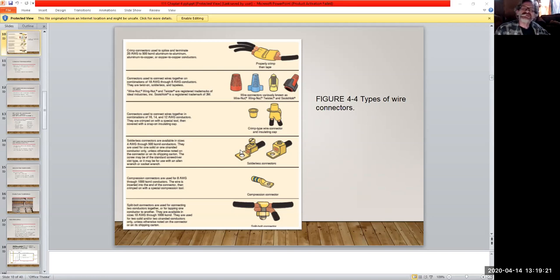And then the common one that you'll see more often than not, I'll get into that in a minute, but more often than not you'll see these types here, the wire connectors. These are the screw-on types, and these days, usually on the outside of the container, each color will tell you how many wires of a certain size joined together can fit within that style of wire nut.